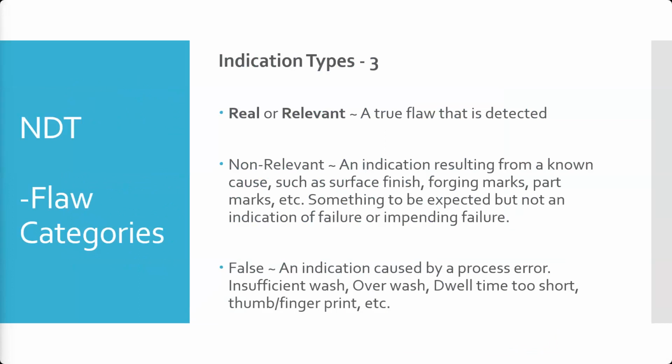and I didn't really get too much into the details. They said NDI, NDT, NDE are pretty interchangeable. The difference you'll often see is that non-destructive testing is performing the test itself. NDE, non-destructive evaluation, or NDI, non-destructive inspection, are in that same category, both kind of looking at finding the flaws. So they're very interchangeable. NDE, non-destructive evaluation, is taking what you find, what you observe, or what your results are, and making some kind of a determination on them.